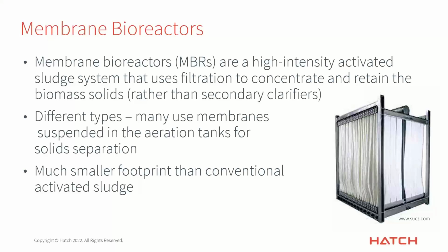So there are many different types of MBR systems, but some of the most common ones, like the one that we're showing here, that hollow fiber system, are arranged in cassettes, and very often they sit right in the bioreactor itself. And the idea is that you want to basically have them sitting right in the mixed liquor, and then you filter, take a permeate out through the membrane surface, and you hold back all the solids, keep back all the good bugs that you want to keep, and get very low solids in your effluent, basically 0 solids coming out, and then your treated water will move on that way.